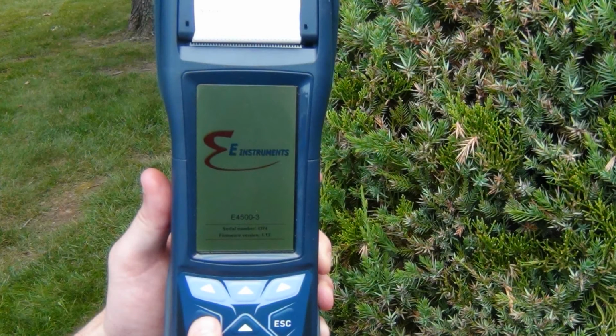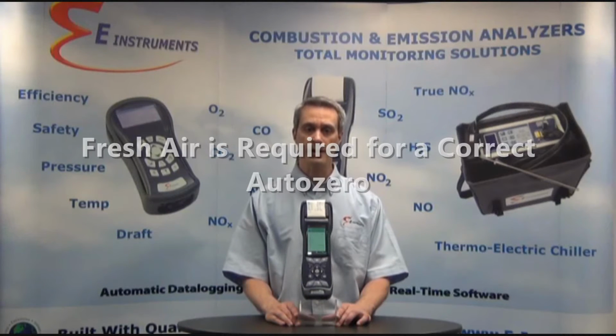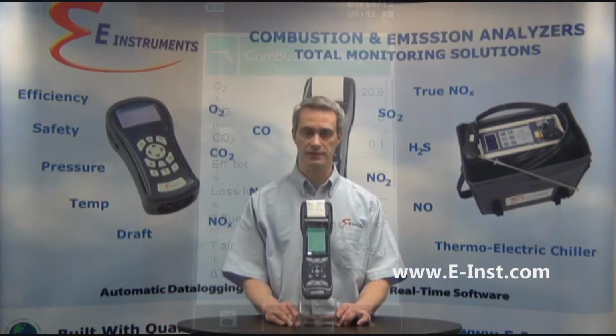Also, it is recommended that the unit is turned on in fresh ambient air, preferably outdoors, for the 60-second auto zero cycle that runs each time the analyzer is turned on. Being in fresh air and not having any of the hoses plugged in will ensure the unit is clear of combustion byproducts and auto zero properly for accurate testing.